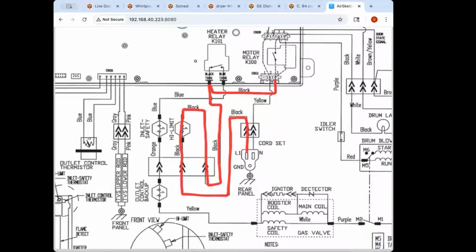It would work in standby, but as soon as you start a cycle, the UI would go blank. If you power cycle it, would it come back on, or was that a one-time thing? No, it was a recurring thing, and the tech was working off a customer description and had difficulty replicating it. So this is kind of a war game based off the symptom that was being reported.